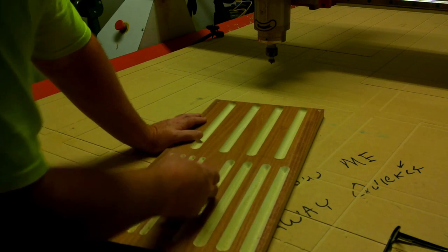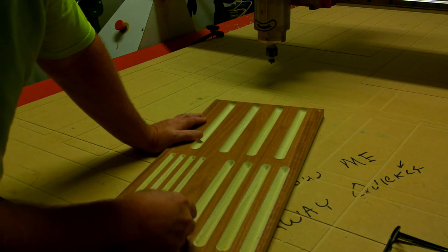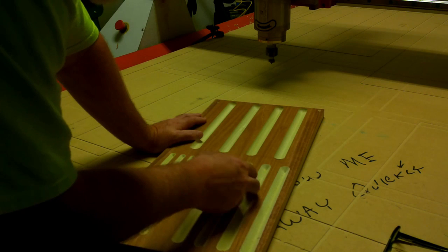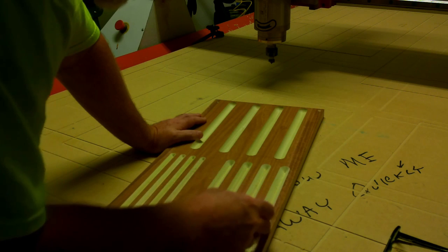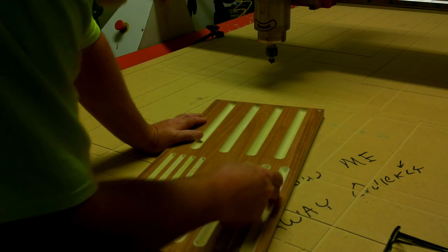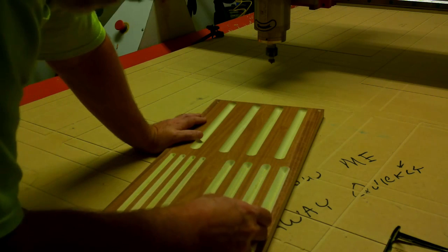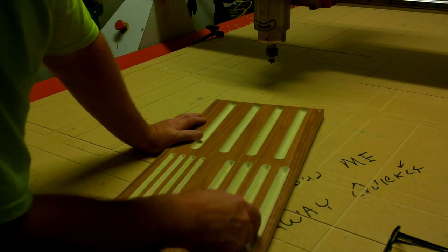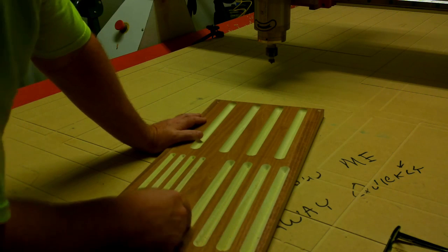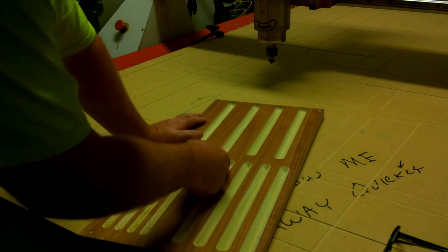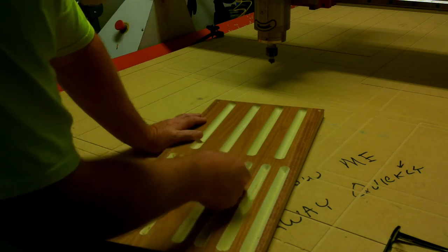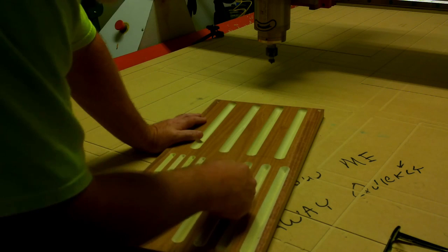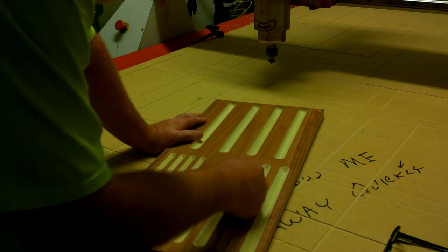The second in quality is the V-bit. And the problem with the V-bit is every single one of these has got a little bit of roughness down in the bottom. Let's just call it doo-doo. Okay? But the best one is the fastest, 18,000 RPM. The slow one actually did pretty well too, but for some reason the 14 and the 16,000 RPM, the 16,000 is just really coarse and rough.